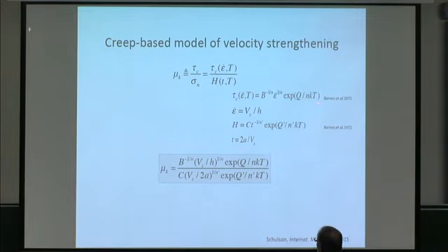And so we invoke here expressions Barnes, Tabor, and Walker gave us so many years ago. For the creep rate, I'll just take it out and reverse the expression for the shear strength. I'll take the hardness and again take it out separately from the way they had done it. And I'll talk about the time of contact of an asperity in terms of the asperity diameter divided by the velocity of sliding. Putting that together gives us an expression for the coefficient of friction.